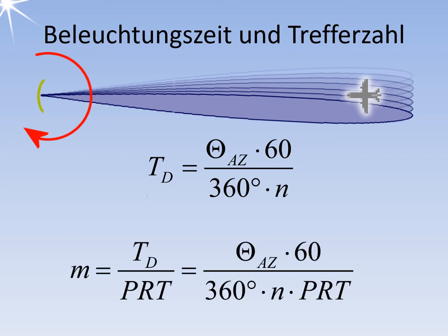To enable radar systems to evaluate the target information with sufficient accuracy, hit numbers of 1 to 20 are necessary. This number depends on the working principle of the radar system. A monopulse radar can process 1 hit per scan but needs up to 3 hits for Doppler processing.